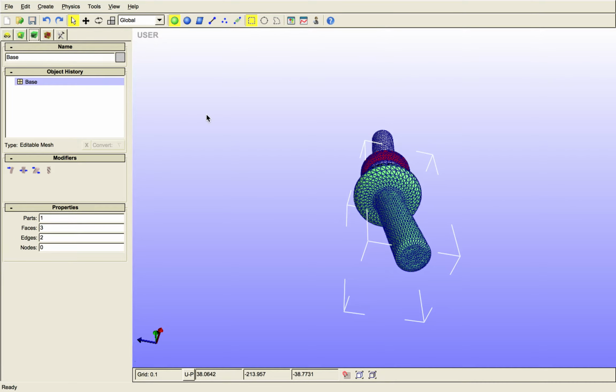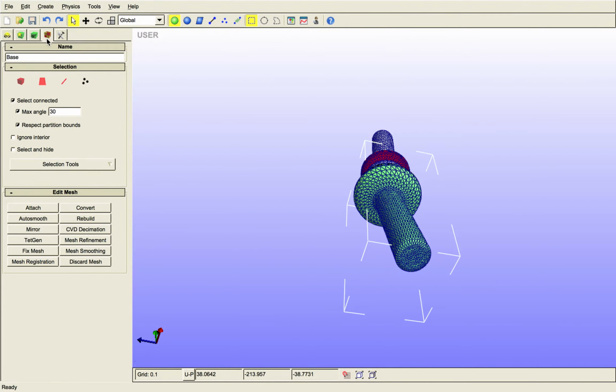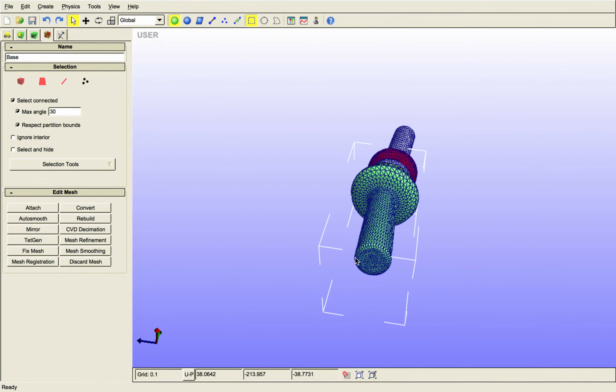This is for modifying the geometries if we want to impose some distortions or some flexions or so on. But we're not going to use this one either. Turn to the next one on the right, and you have mesh. For mesh, you can choose this, and you have different tools. As it's already meshed, we're not going to get into detail on this, but the main point is that whenever you have selected an object and you want to select element by element, you have to hit this button, select faces,